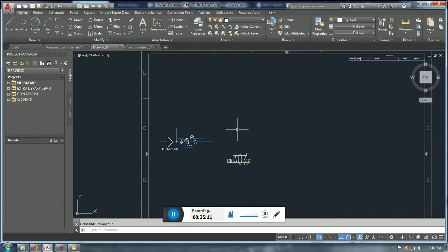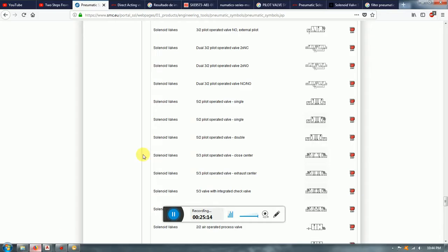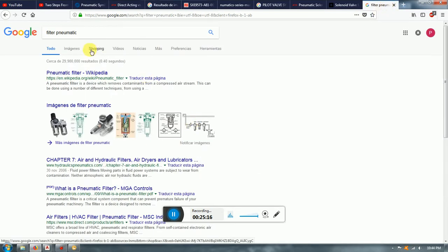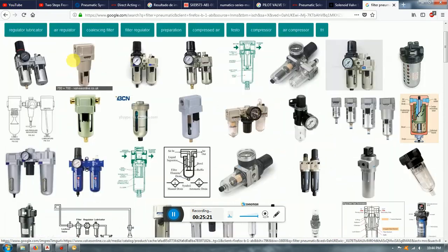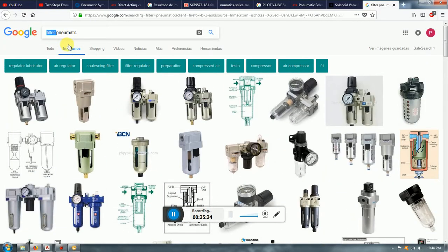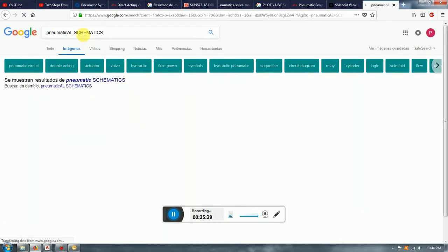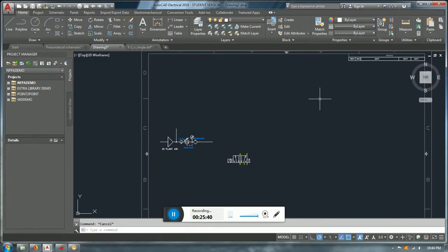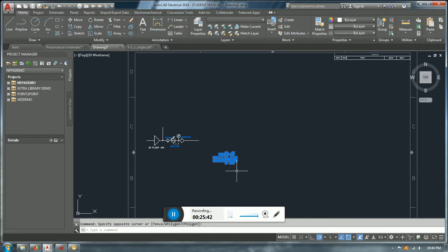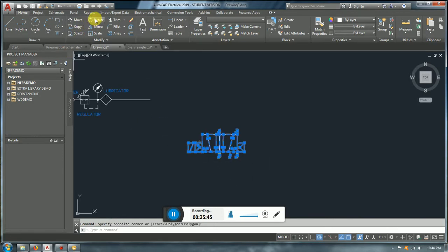So now it depends. You want to face cylinders up or down. Typically, you're going to see examples where things are facing, and in any pneumatic schematics, it's going to be the cylinders up, typically, right? Doesn't matter. As far as I know, I didn't see anything in the standard telling me the opposite. I like pistons down. I guess that's odd. So we're going to mirror that.